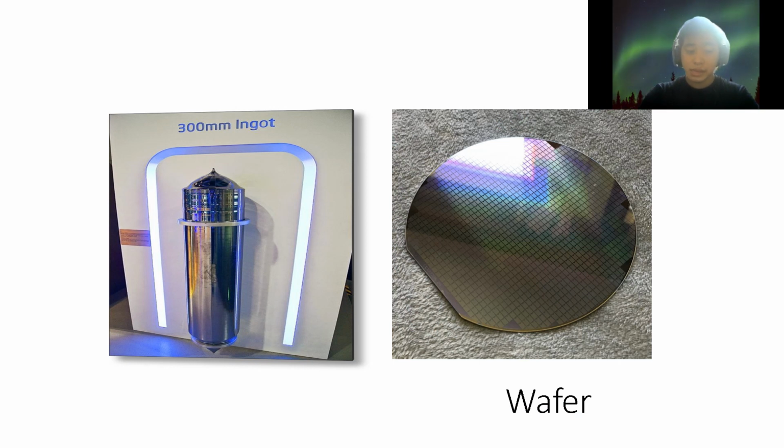After all those steps, it needs to be polished. That's why the last step is wafer surface polishing. The thin slice obtained through the above-mentioned cutting process is called a wafer. That is an unprocessed raw wafer. The wafer surface is uneven and it is impossible to directly print circuit patterns on it. Therefore, it is necessary to first remove surface defects through grinding and chemical etching processes. Then, form a smooth surface through polishing and then clean residual contaminants.